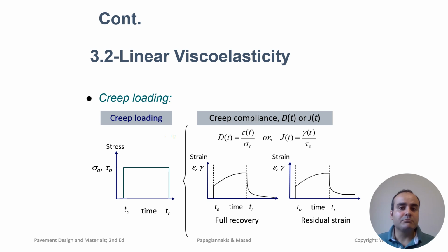High temperatures make asphalt more prone to creep as the binder becomes softer and less resistant to deformation. Over time, if the stress is high enough or the temperature is too hot, this deformation becomes permanent and can lead to rutting, which is a form of surface deformation where the pavement exhibits longitudinal depressions in the wheel paths.